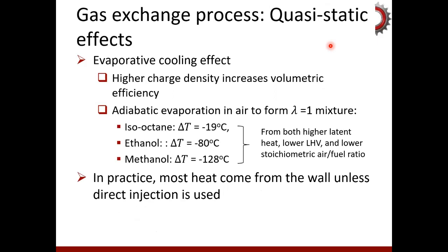Another quasi-static effect that we observe in internal combustion engines is the evaporative cooling effect, particularly in the intake system. Especially if it is a spark ignition engine, then we introduce fuel into the intake system, and the fuel will evaporate and cool down the intake air. Accordingly, there can be situations where the density is increased and the volumetric efficiency is increased.